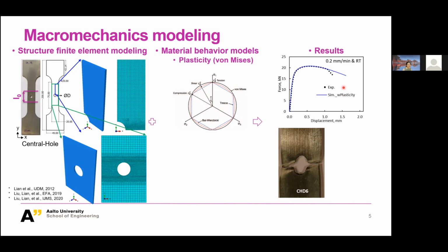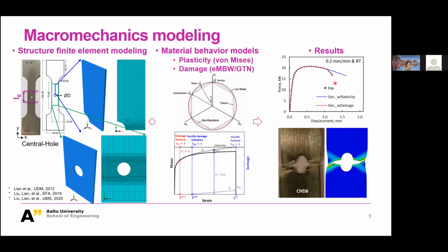And you see here with the MS model, there is no damage part. So you see the micro simulation result can give you a good prediction compared with your experimental result in the elastic and plastic part. But after damage happens, your model cannot capture the drop of the force. So furthermore, we will also have a kind of damage model, for example what you learned from the literature, the GTN or JC model. With this damage model, you can see that it can predict this drop of the force caused by damage or final fracture with quite good agreement with our experiment. And furthermore, after the deformation, you will see this deformed pattern. This also has a higher agreement with your experiment.